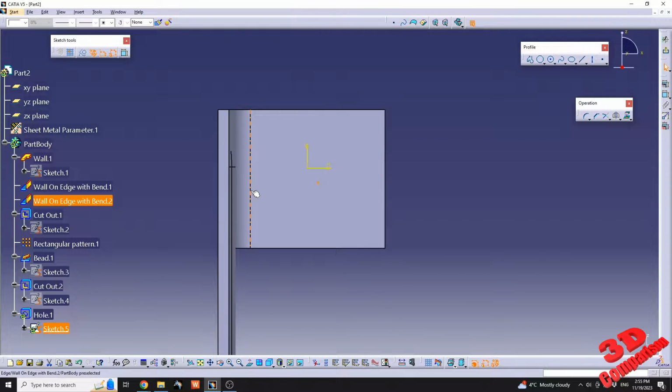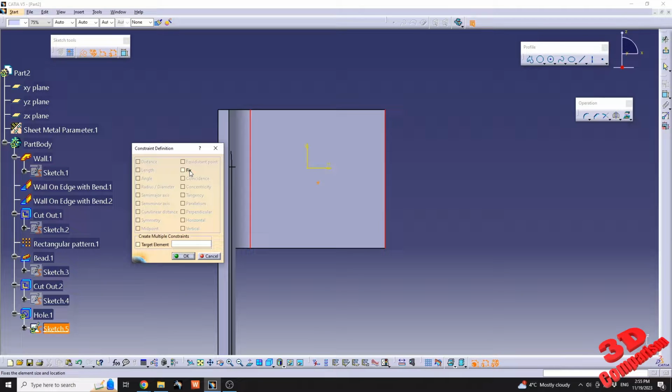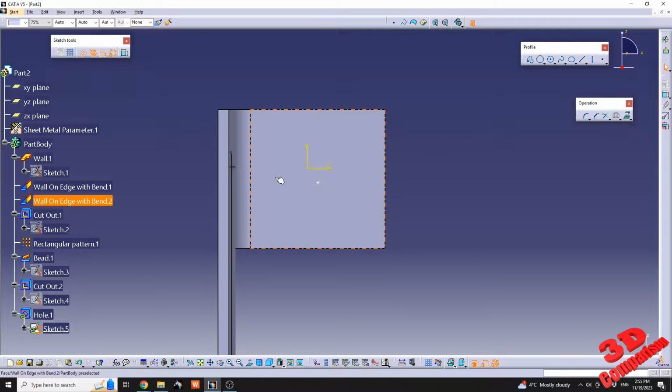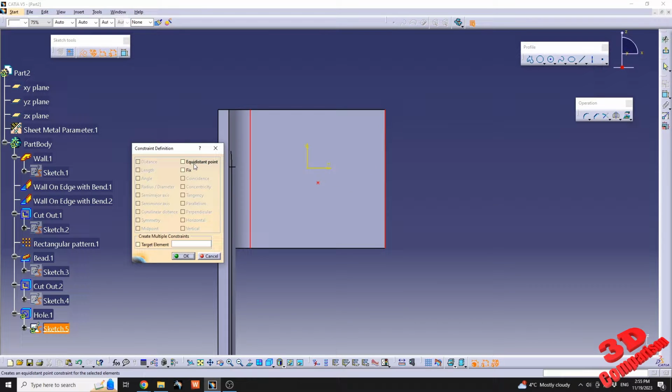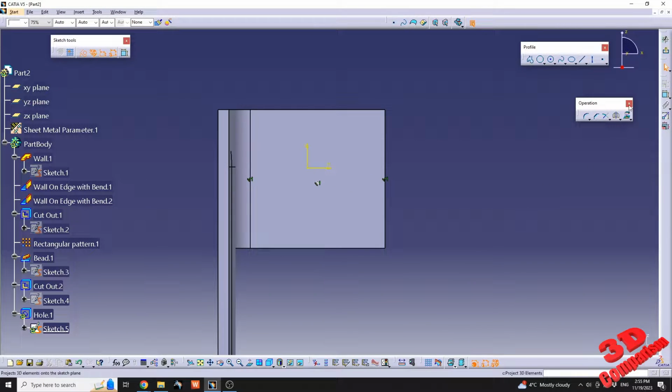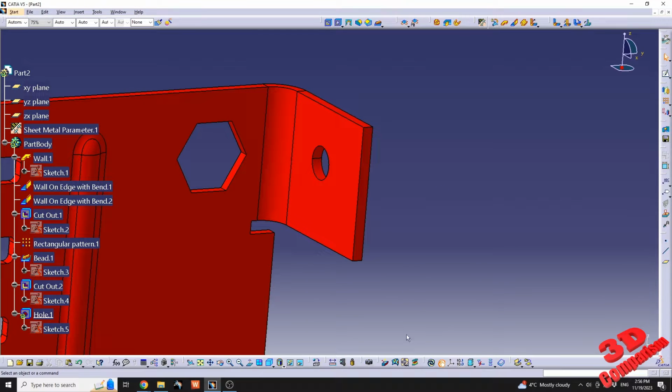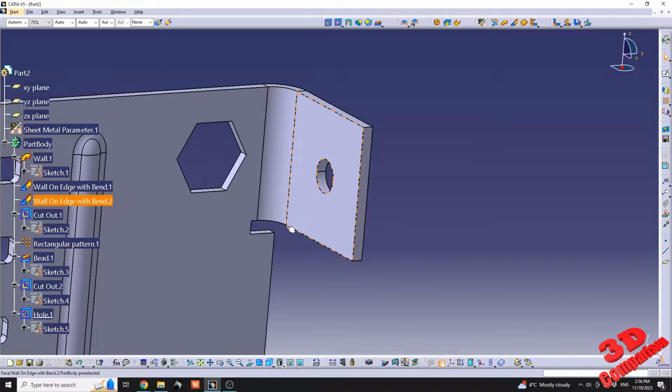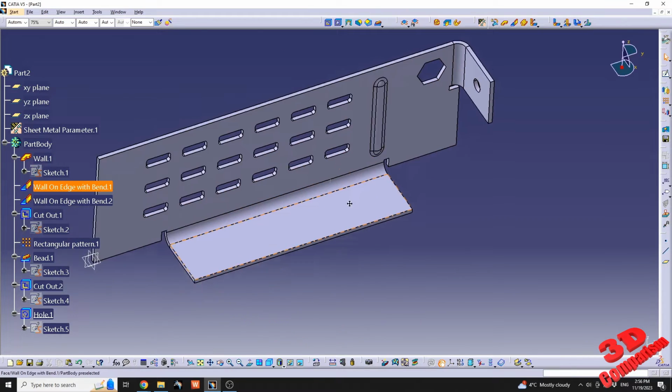You can have this either positioned like this, so we can make use of the equidistant point, but in order to do that you need to select the two edges first while holding down Control, and the point should be last, and afterwards you have the possibility to center it like this. Or you can center it directly with a dimension. In this case we know that 10 will be to center that, and after we're gonna do a local update, we're gonna have that changed.